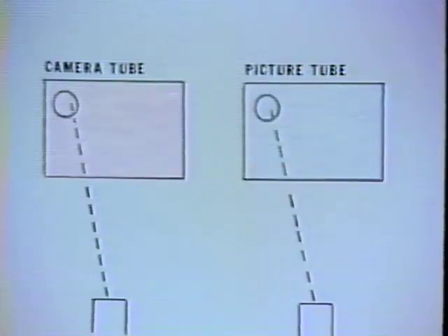We have seen how a picture focused on the target of a Vidicon tube is scanned and dissected by the electron beam of that tube, and how another beam in a cathode ray tube scans the phosphor surface, causing it to glow and produce a visible image. What we must now look at is how the two beams scan the target and the picture face. Obviously, both beams must be at the same point in the picture at the same time. They must be synchronized. This is the same situation as with the cell and the lamp in the wire photograph. If the two beams scan in step, then a faithful copy will result. If they are out of step, then the copy will be of no use.